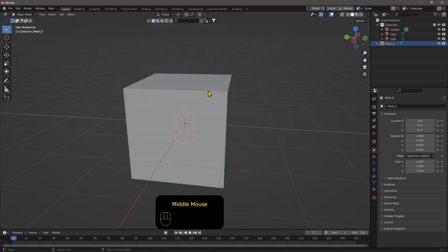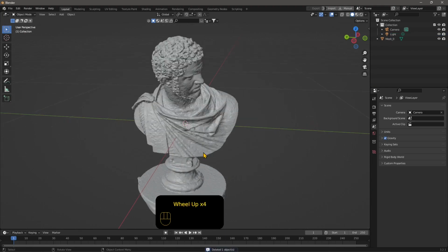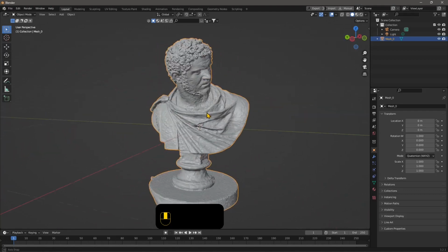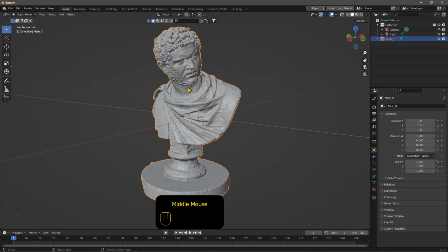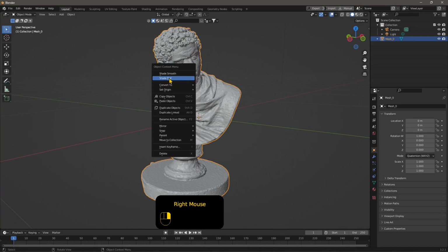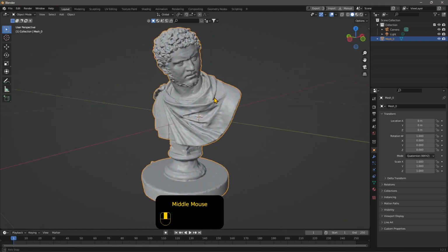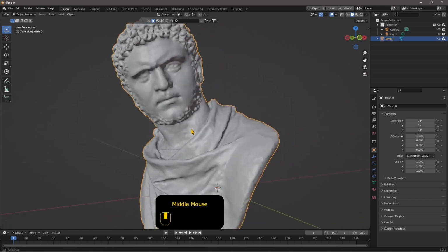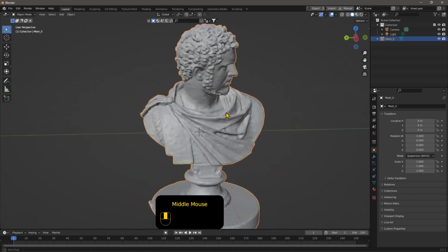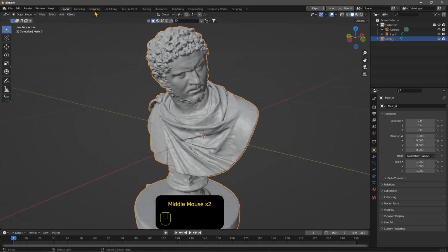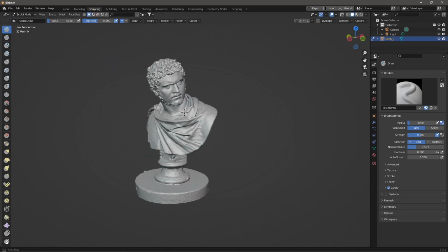Now it's in Blender. Now I'm going to get rid of this cube for the moment because I want to concentrate first on the integrity of the mesh. So the mesh is essentially a 3D model and is composed of polygons, vertices, edges, and so on. First thing I could do here is change from shade flat into shade smooth. Shade smooth will create a nicer effect, a soft mesh surface, and I think it's going to be more accurate and give a better result than using the flat shading. So that's the first thing I could do in terms of viewing the model.